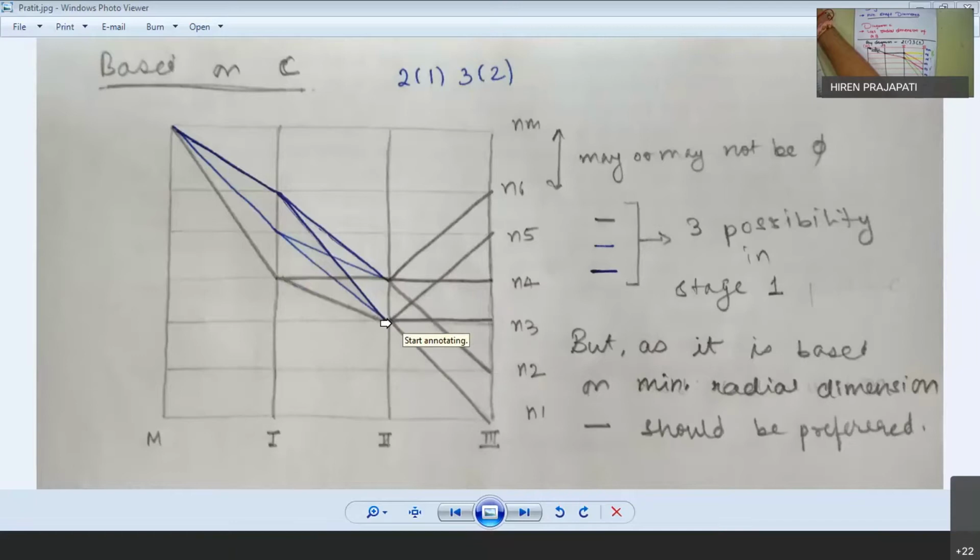Whenever we position our node such that the increase in speed and reduction in speed have the same geometric progression power, at that time we get maximum reduction. So for stage 3, this is fine. So we have considered N1, and we got N3 from N1 by one line, because we get 3 speeds from a particular gear cluster and 2 is the characteristic number.